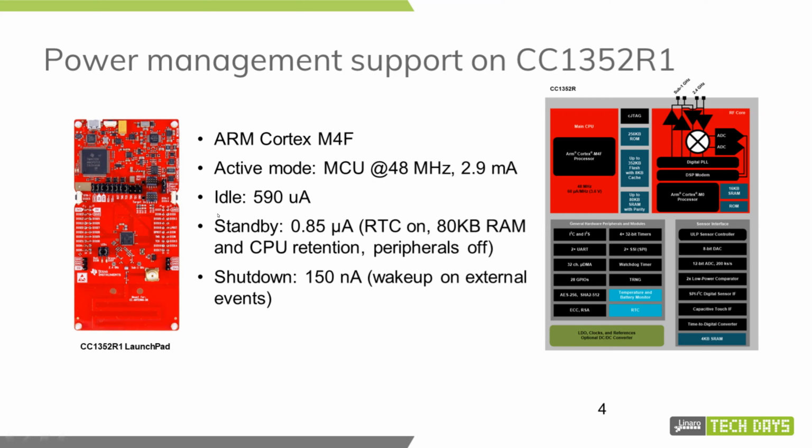It supports 3 low power modes: idle, where the CPU and the RAM are clock gated, so it has very low latency. And then there's a standby mode where the CPU has retention, so it knows where to resume once it comes back up out of sleep. In that case, the real-time counter or real-time clock on the device is left on, but other than that, all the other peripherals are turned off. So it's a fairly low power mode. And then there's also the shutdown mode where really everything is off except for the I/O being latched, and it's ready to receive input from external events, such as a button push, for example.